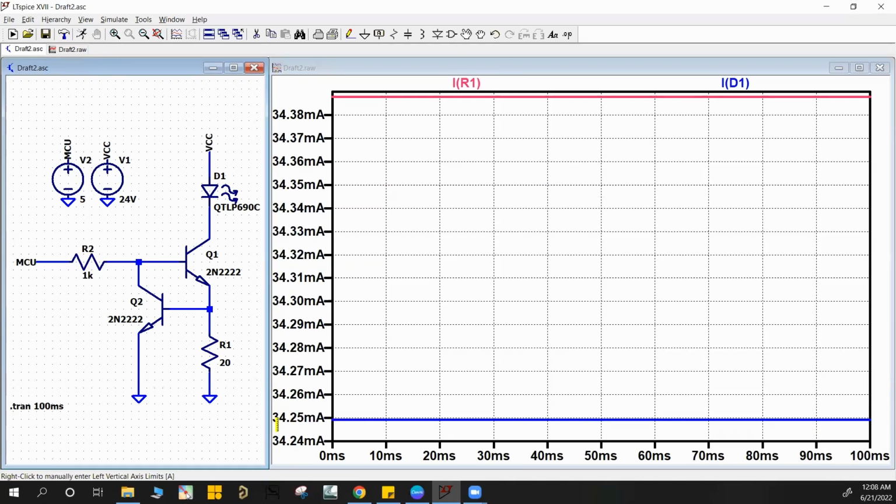And as you can see, it's exactly the same current. I think it was like 22, it's a little bit higher. Obviously, because of the actual more voltage going through here, the more current through the collector, there will be slight variations. But as you can see, it's very negligible. So again, we ensured that even though we doubled the VCC, the current through this LED stayed the same.